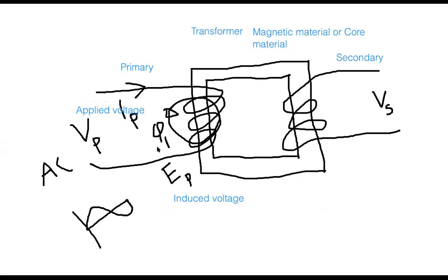Now, for example, this is the picture of an ideal transformer. Ideal transformer means I did not show any resistance. Everybody see, these are the coils, and you all know that coils mainly mean inductance. But in real practice, these coils have some resistance, a very small value in the ohm range, but they have some resistance. At this point, I am not putting any resistance.